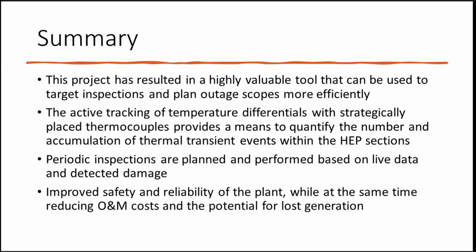And Eugene, are any of these done with pad welds? That's what we always used to use in the fossil plants. I thought I saw some of those in one of the presentations. So we chose not to do the pad welds or the little disc. After consulting with Bob, we felt like the quick response would be more important than the better attachment technique. When you put in a big pad weld, you get all that thermal inertia, and you'll get a slower response if you get a quench or a slug of water.